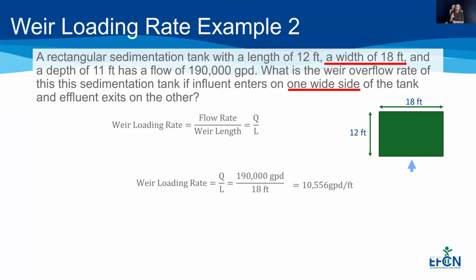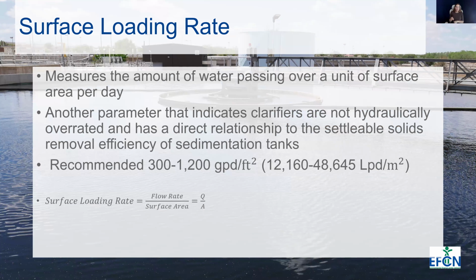Now we're going to move on to surface loading rate, which is a very similar design parameter. This typically measures the amount of water passing over a unit of surface area per day. Like we said, it's another parameter that indicates clarifiers are not hydraulically overrated, and it has a direct relationship to the settleable solids removal efficiency of sedimentation tanks. Because if you have too high of a surface loading rate, you will not have your solids settling correctly, and a lot of them will be flowing over, and you'll be getting some of that short circuiting.